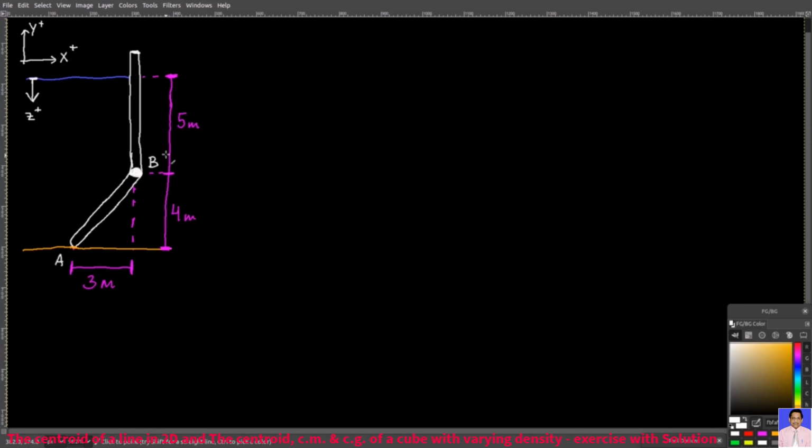I have a wall here, and then on the left side of the wall, you have water here, and this wall holds the water back. And then I have the gate here, this AB section, that can rotate about point B. Right now, the gate is closed. The water that is held back by the structure exerts pressure on the gate AB. Now, the width of this gate is 8 meters.